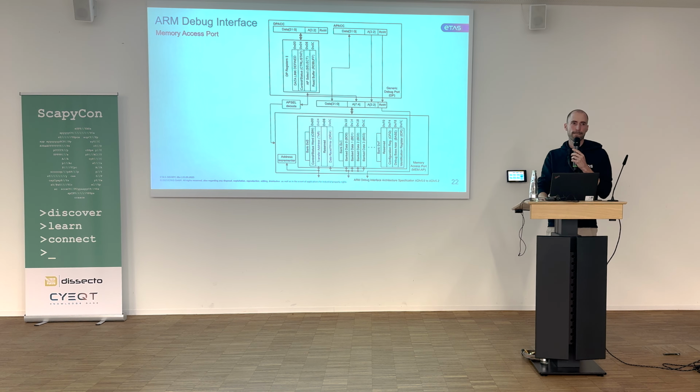In the recording, one could see the green line sometimes move to the injection point. Was it an artifact? Yeah, that's a good question. Sometimes it might be that the trigger for the oscilloscope was not correctly set, and then there was some jitter on the reset line that caused it to trigger on something else. That's one thing. When I saw the recording, I was like, darn.